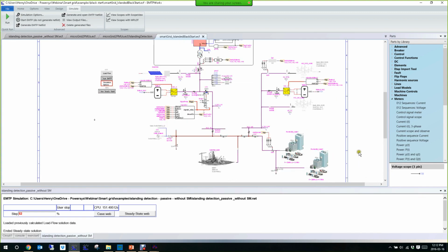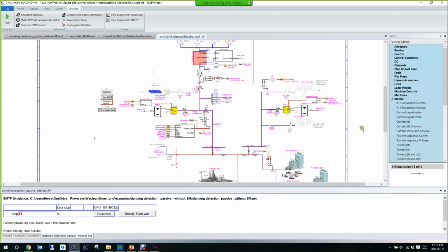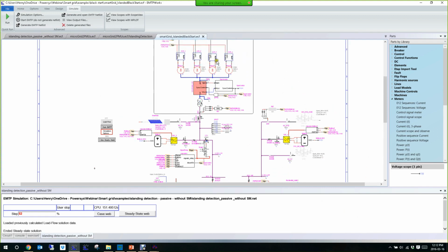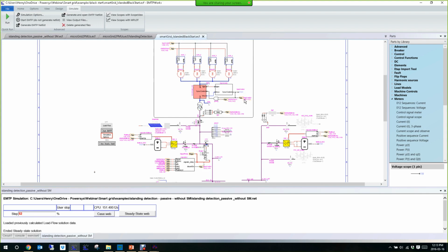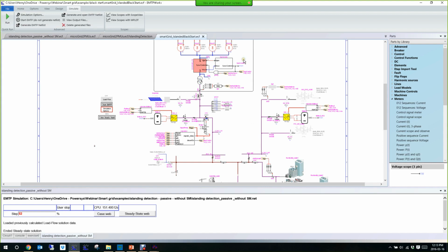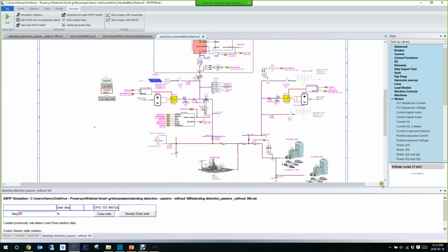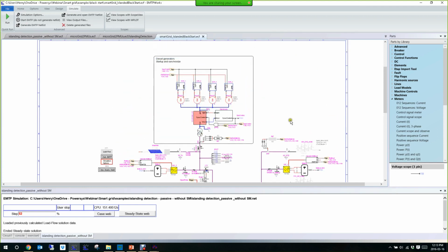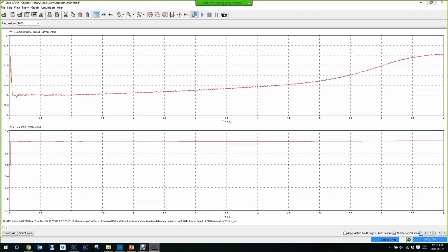First the loads are disconnected. We'll use the battery to first energize this part of the grid. Then we will start those diesel generators. Slowly the voltage will ramp here, and then we synchronize them with the rest of the network. And we will ask them to produce some power. While they produce some power, we will store the power in the battery. Finally, when the synchronous machine reaches the steady state, we will reconnect the residential load, and then the network will be ready to go. Cool, eh? So let's look at those.